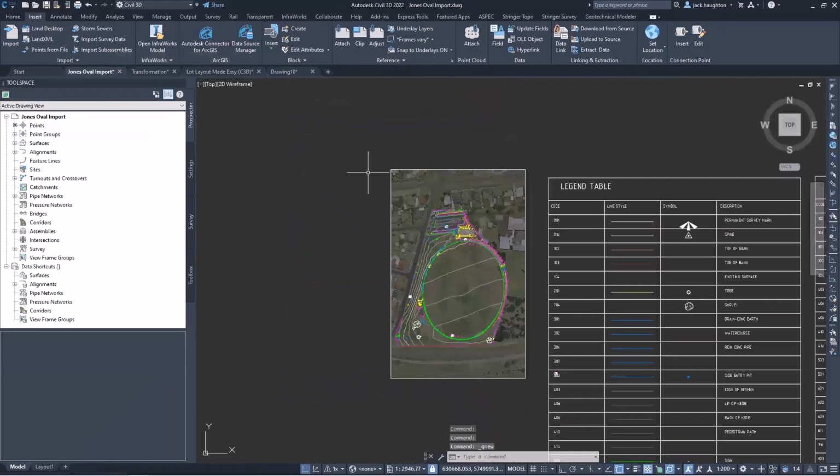With that covered, we've gone through importing using GPS, applying a transformation, applying a least squares adjustment. We've then had a look at importing a raw data file and a variety of different things you can do to edit said file and getting yourself ready for production. So with that, I'll hand off to Shane, unless there are any questions that I should be answering.